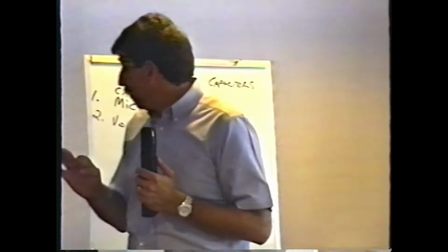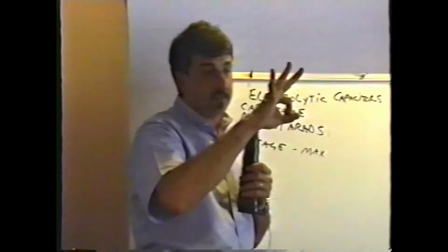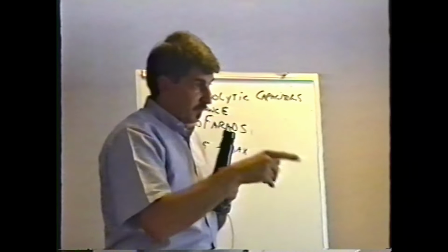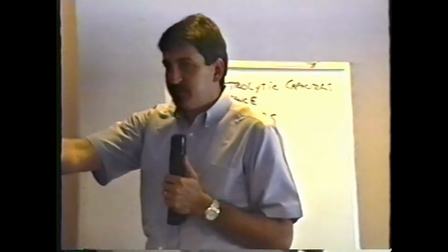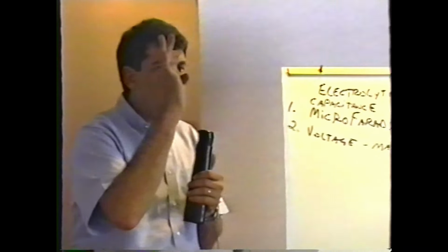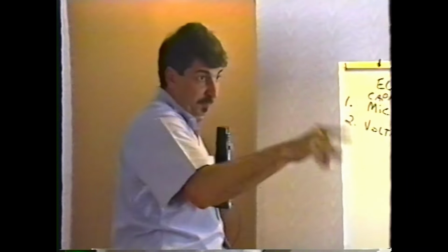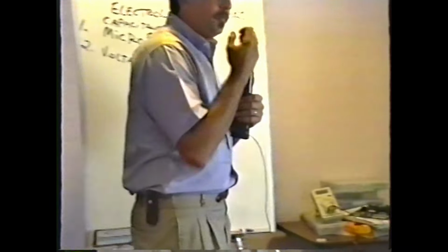We have a hole in the door of our shop that's about the size of a dime. From talking about, let's blow one up. Well, that's exactly what happened in the shop. The guy said, hey, I'm going to blow one up, and he put it over here, hooked it up backwards, and it shot a good 10 feet over to the door and just blasted a hole in it. So be careful, like your mom said, you can put your eye out with that thing. You've got to really be careful with capacitors. It's entirely possible if you put them in backwards that they'll blow up.